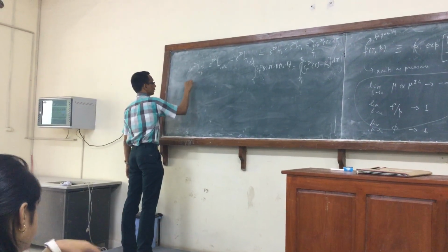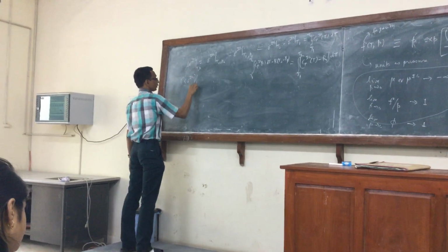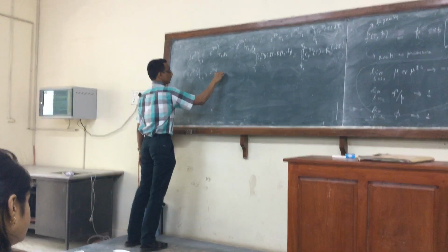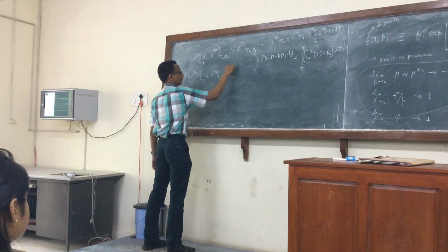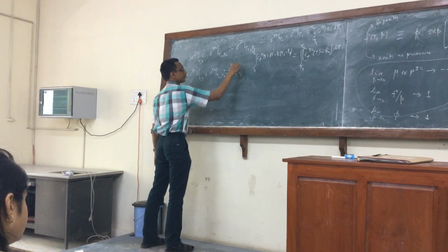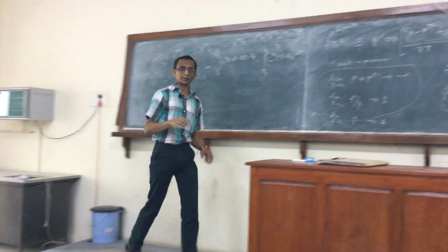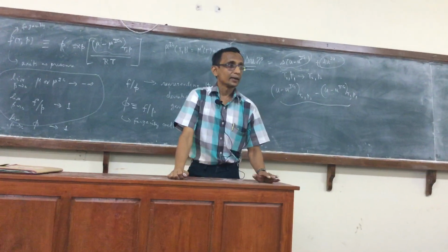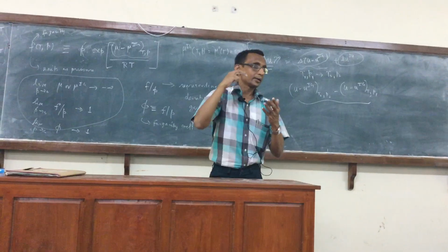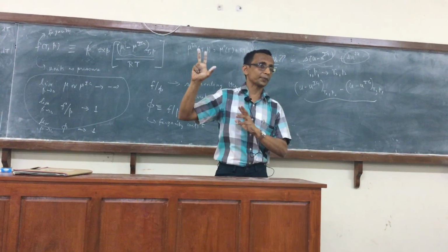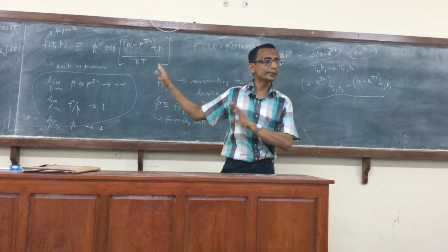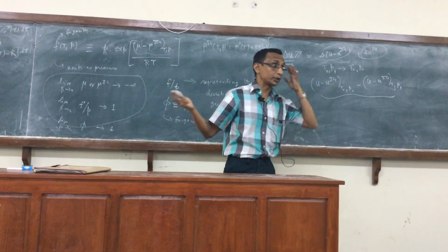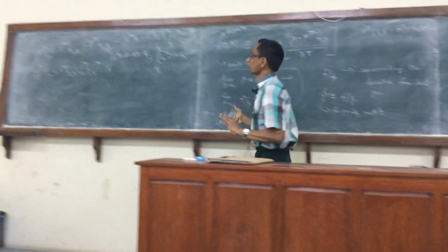Now delta EIG at T2, v2 minus that at T1, v1 is the same as this, because anyway the internal energy is a function of the temperature of the ideal gas, right? So it doesn't matter whether I specify the change of state of the actual substance in terms of T and P or T and v. This change of the ideal gas specific internal energy is not going to change. So I get the same formula.